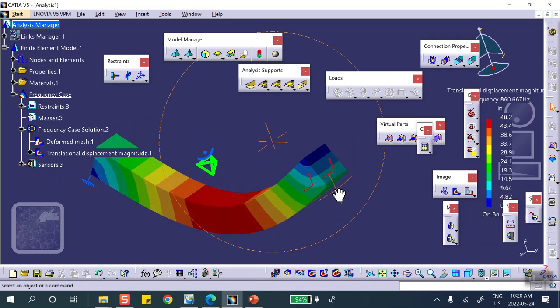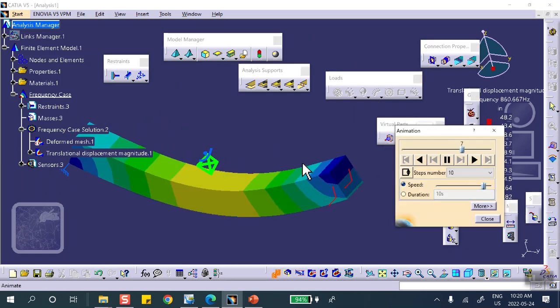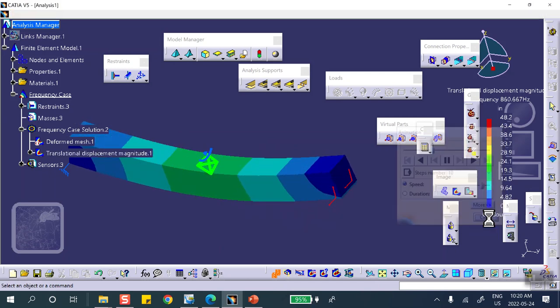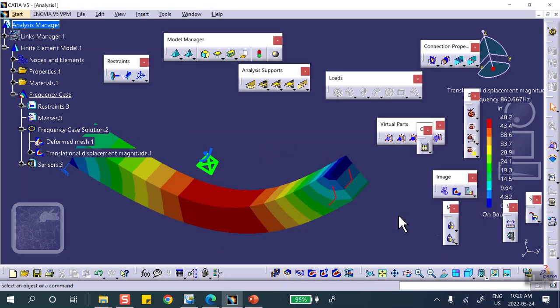Okay, so mode of vibration, yeah. Okay, how much is that? How much does it deflect? Yeah, 48 inches. The whole thing was 10 inches. This is deflecting 48 inches because when you do natural frequency calculation, the only thing that's correct, the only thing that makes sense is the frequency and the shape of the mode. Deflections are garbage, the stresses are garbage.